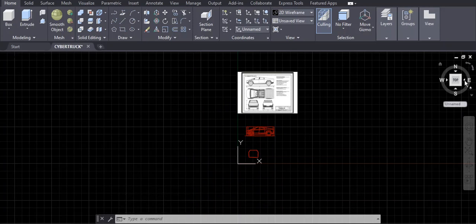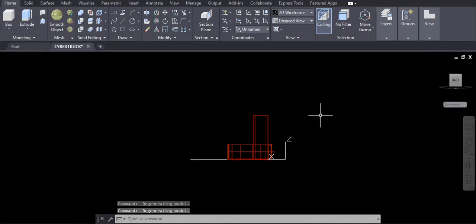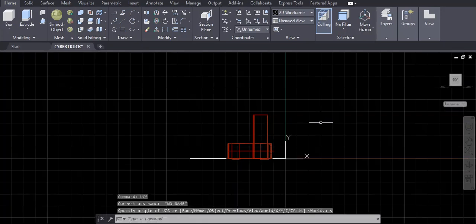So I'm going to go to the east view. Actually, in order to rotate the front view, I need to go to the view above the front view. So click on the top view. Okay, this is your front view. This front view has to be rotated. But remember, UCS has to be rotated too. So Z should be perpendicular to you, XY should be parallel to you. So that's why I'm going to change the UCS. Enter V for view. Okay, now XY is parallel, Z is perpendicular.